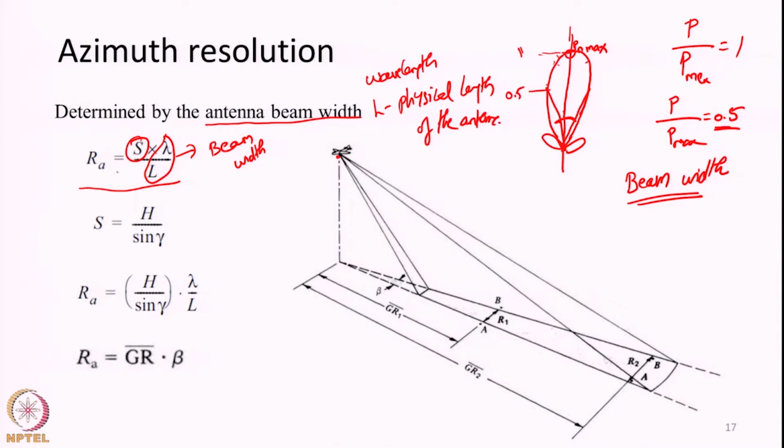So, this suggests that the azimuth resolution will become larger and larger, or coarser, when the slant range distance increases; that is, the antenna beam will be spreading continuously when it is transmitting. Whatever objects fall within one full beam will be imaged as one single pixel.